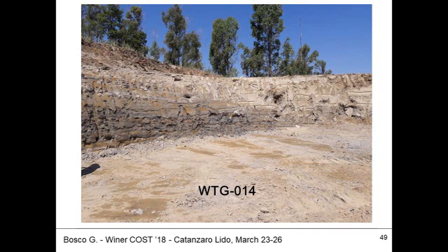So the simplification led us to consider a water table over here, assuming the water table 2 meters above the level of the foundation, thus reducing the strength of the material and running an effective stress analysis.